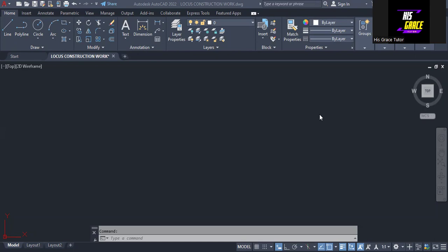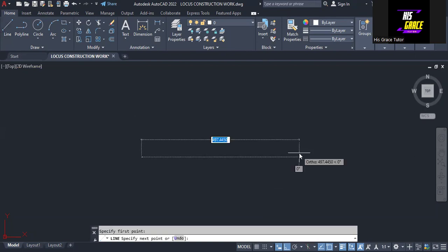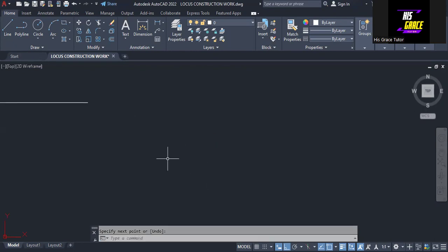So what we have to do first is to draw the major and the minor axis, and it goes as follows. So we need to put on the auto mode. We need to make sure we activate it, we enable it. So then we go to line. Then we have to draw a horizontal line, which is going to stand for the major axis, 120. So enter. All right, so we have it like this.